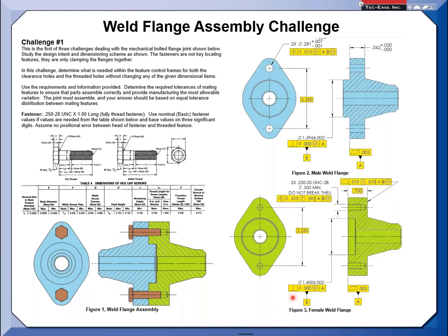Depends upon the company. No, that did. Thank you very much. I see what you're saying, because you just have one primary datum. Right, right. But have I seen companies put position here? Yep. Me myself, I could look at that and extrapolate: oh, yeah, they've got position, but really the only thing going on is an orientation control. So it really doesn't cause me heartburn in that case.